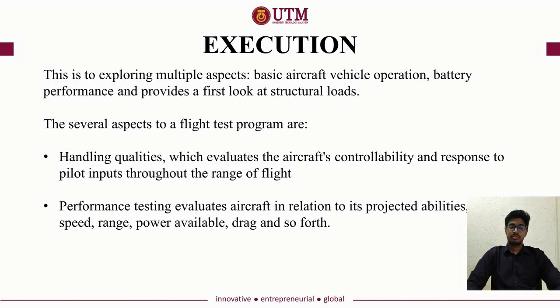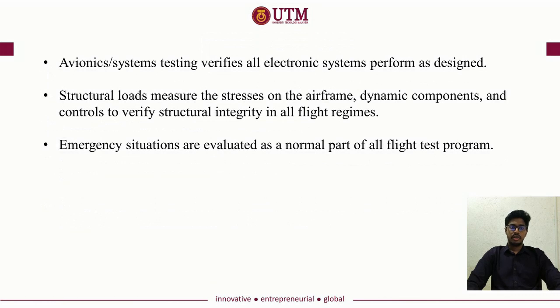which evaluates the aircraft's controllability and response to pilot inputs throughout the range of flight. Next will be performance testing, which evaluates the aircraft in relation to its projected abilities, such as speed, range, power available, drag, and so forth. The other will be avionic or system testing, which verifies all electronic systems performed as designed, and structural loads that measures the stresses on the airframe, dynamic components, and controls to verify structural integrity in all flight regimes.